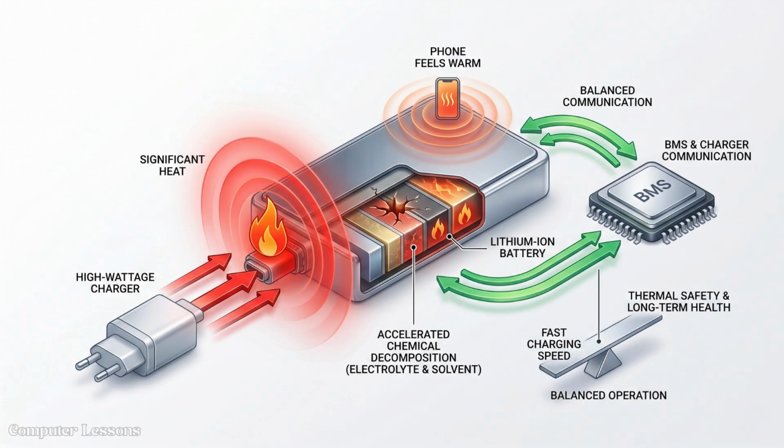Heat is the ultimate enemy of battery longevity, accelerating the chemical decomposition of the organic electrolyte and the solvent. Fast charging generates significant heat, which is why your phone feels warm when plugged into a high-wattage brick. Modern chargers communicate with the device to balance speed with thermal safety and long-term health.